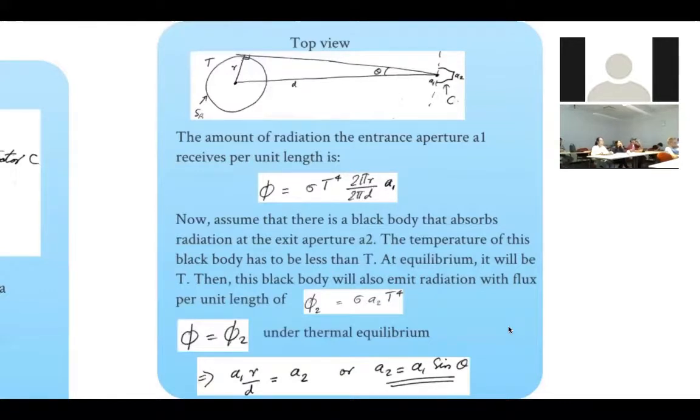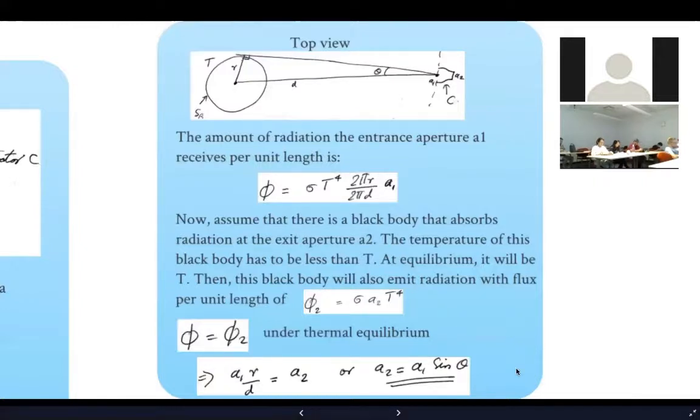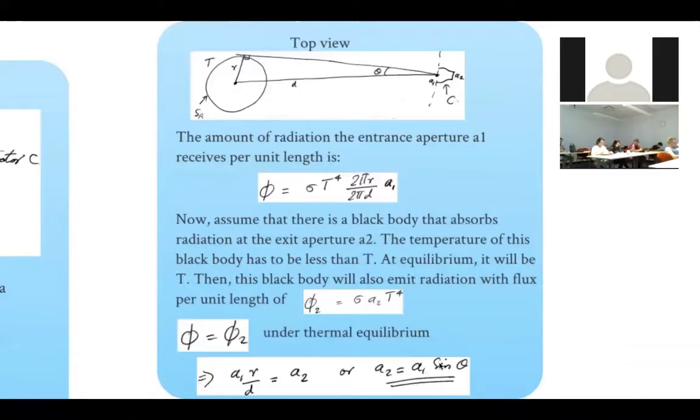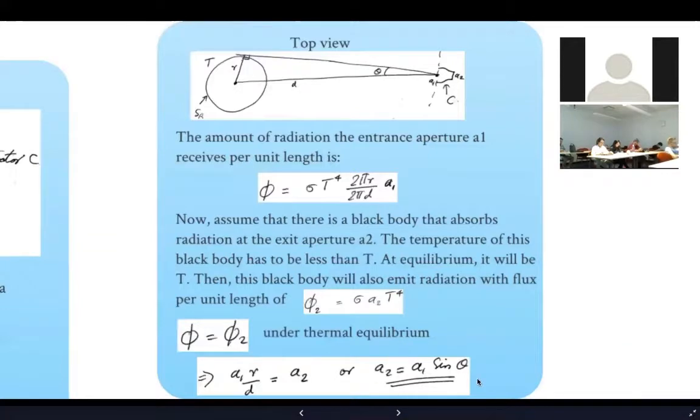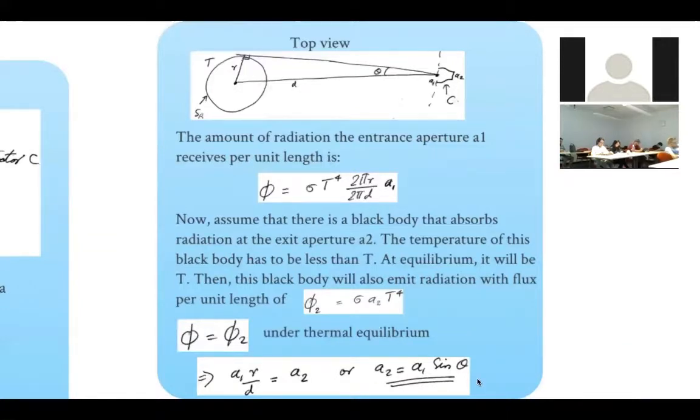And we have made no assumptions as to the shape of the concentrator. This is very, very important because we end up with the same expression without making any assumption on the geometry of the concentrator. And we know that this condition is held for the CPC. So the only conclusion we can draw now is that the CPC provides the thermodynamically ideal or best concentration that is possible.